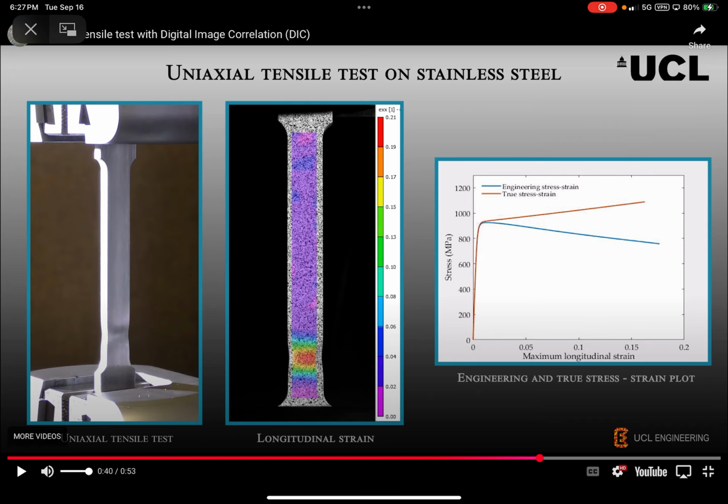Pay close attention to the bottom. You guys see what's happening? Here's a little diagram showing how the strains are developing. So you guys notice, once you reach this point here, we call this point yielding. Once the material yields, we generally consider it failing because we don't want the stress to exceed any higher than that. Otherwise, you start running into the problem of really large deformations, which is something we call plasticity. We do not want that usually.